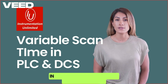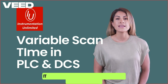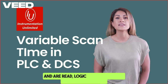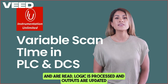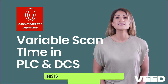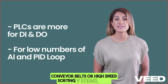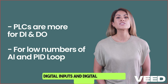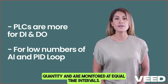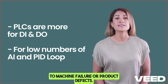Why? In a PLC, real-time deterministic control is crucial. It executes a fixed scan cycle where inputs are read, logic is processed, and outputs are updated, all within a predefined time. This is essential for processes like robotic arms, conveyor belts, or high-speed sorting systems, where digital inputs and digital outputs are in large quantity and are monitored at equal time intervals. Any delay or inconsistency could lead to machine failure or product defects.